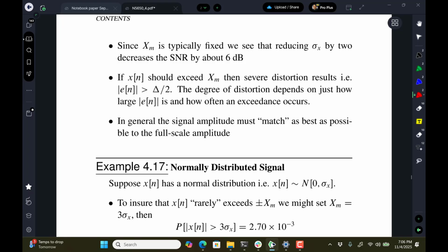In the project I worked on, the space radio project, they had a rule of thumb of a 10 dB overhead. So that means you anticipate if the signal maximum level is going to be thus and such, you provide 10 dB more of headroom before you bang against the levels of your quantizer.